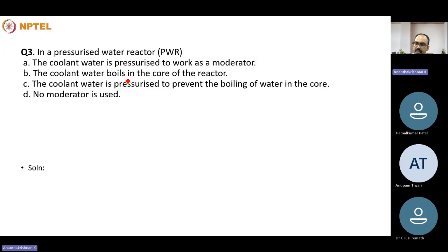Since in the boiling water reactor, steam is directly produced by boiling the water coolant, the steam is then separated from the remaining water in steam separators positioned above the core and then passed into the turbine. The steam is later condensed just like the normal Rankine cycle and recycled.